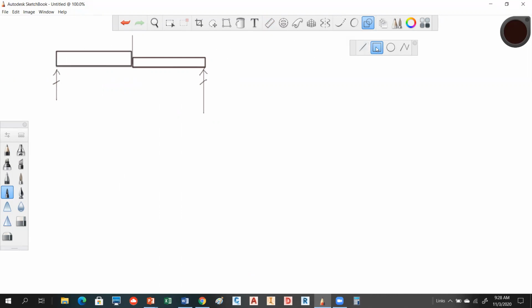Okay. And we're going to have loading rates on those guys. Let's see. This guy's going down and these guys are going down as well. They could go up, by the way. So that could impact what you're doing. So we're going to have 10 kips here. This one is going to be 1 kip per foot. This one is going to be a load rate of 2 kips per foot. And we're going to give you the reactions, so we'll just step through that. Okay, so this is going to come out to be 17 kips, and this turns out to be 22.5 kips.